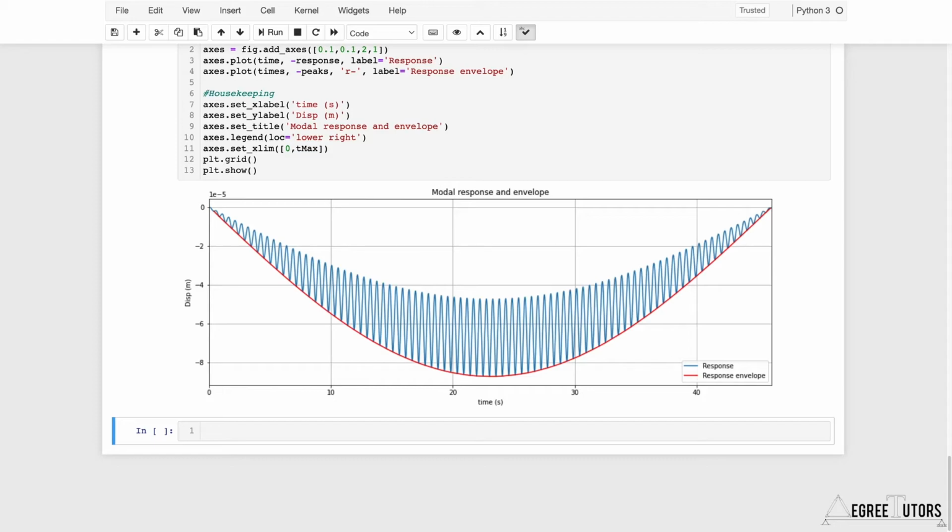Now, intuitively, we can say, well, the heavier the bridge deck gets, the lower the natural frequency. So if your natural frequency is starting off quite high, above the average pacing frequency, the heavier your bridge gets, the lower that natural frequency is going to get. And it's going to bring it down closer and closer to your average pacing frequency, which is generally bad news. And that's what we're going to see here.